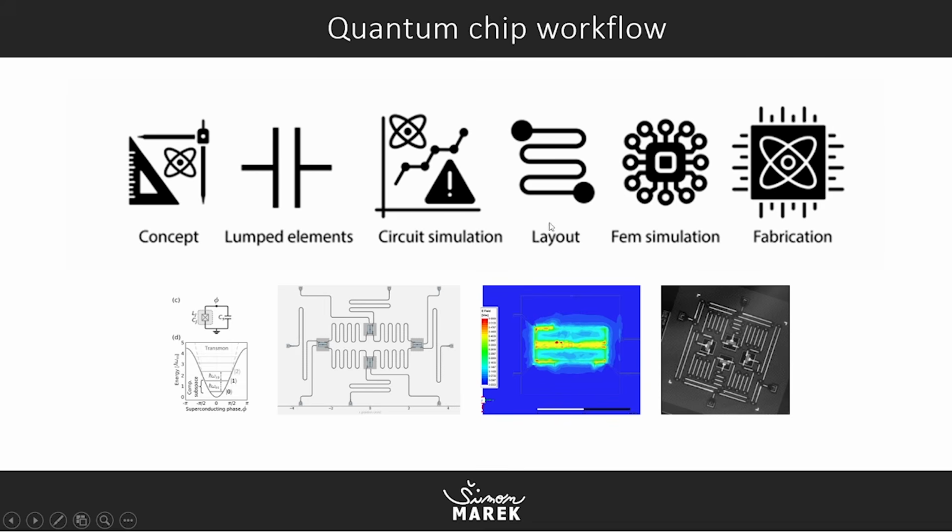Then you need to do the layout of the RFIC chip, and then you might need to simulate some properties of the layout, so you can export it into some FEM simulation and really simulate the real inductance of the on-chip inductors, so you know the calculations from your tools were correct, and you will get your RFIC as desired.